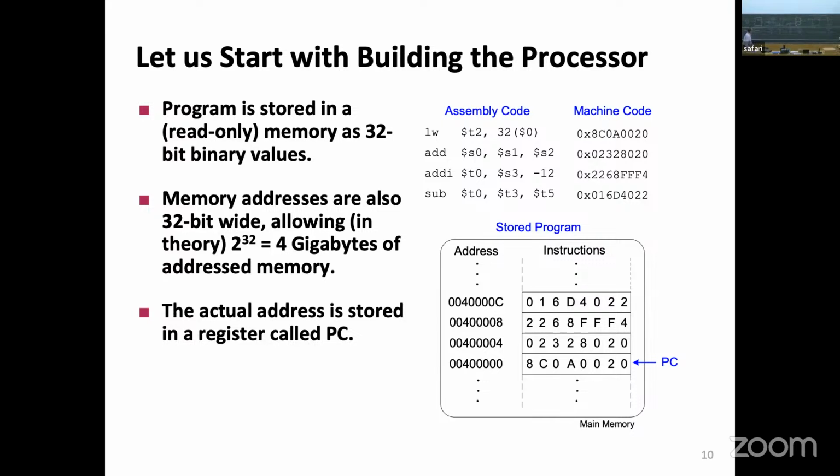Now let's take a little look at what we made. We manipulated things the following way. I just had R-type instructions, and now I added some of the I-type instructions. Specifically, I added the support for LW, load word. And load word I know because the operation code will be 100011. Once I read the instruction from the program counter, going here, the control part will realize that the operation is this, and then we'll be able to make the decisions about which multiplexer should have which value.